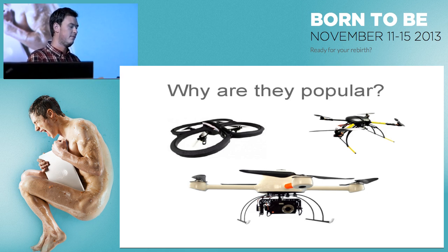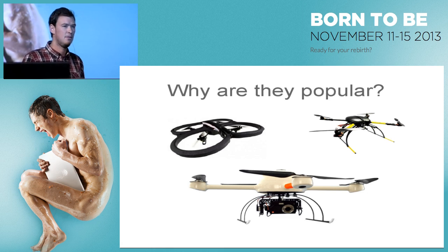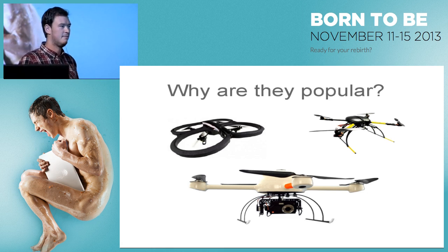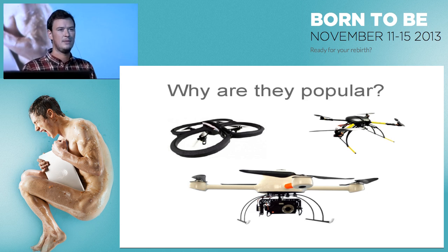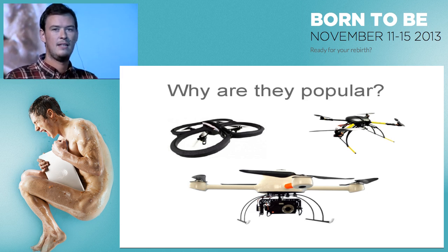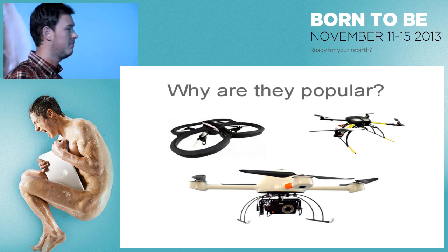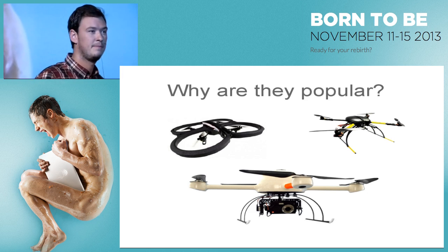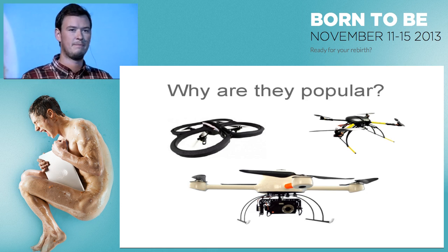Since they have 4 smaller rotors, they build up less kinetic energy. So in case of a crash, they are a bit more crash resistant, and also they're not as dangerous. And also the mechanical simplicity is a lot better. You just put 4 motors on the frame, and that's about it.